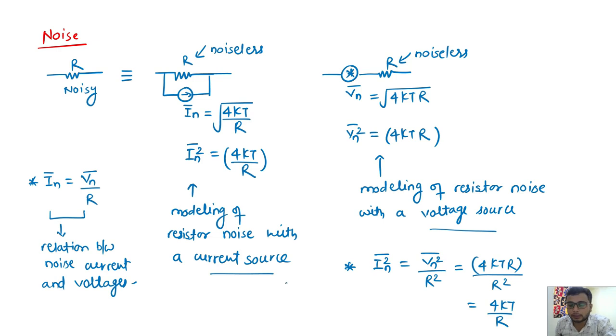Now I will consider the noise of the amplifier. So here the amplifier is a 5 transistor OTA inside it. I'll directly model it. If there is an amplifier given, you can simply model the input referred noise at the non-inverting terminal. This is called V noise of the amplifier. And how it can go to the output, there are two ways. So this is the noise model, and whatever the circuit is here, I don't care.